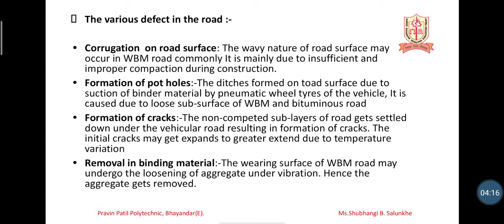The second is the formation of potholes. As you know, in day to day life, you can see at least one pothole on the road. So let me see what a pothole is. The ditch formed on the road surface due to suction of binding material by pneumatic wheel tires of the vehicle. It is caused due to loose subsurface of WBM and bitumen road.